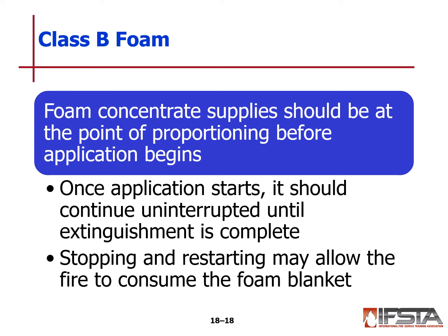Foam concentrate supply should be at the point of proportioning before application begins. Once this application starts, it should continue uninterrupted until extinguishment is complete. Stopping and then restarting may allow the fire to consume some of the foam blanket that we've already applied.